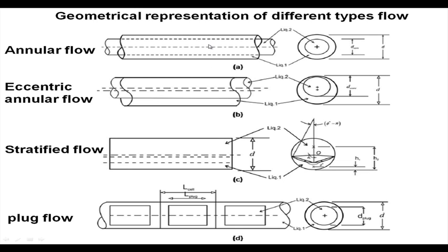So, we have developed energy equations for both of them, such that we can see under what condition the eccentric annular flow becomes more stable than the concentric annular flow, or in other words, the eccentric annular has lower energy content as compared to the concentric annular flow pattern. But in both cases, we have assumed smooth interfaces between the two liquids.